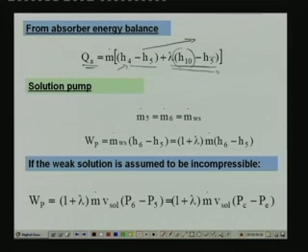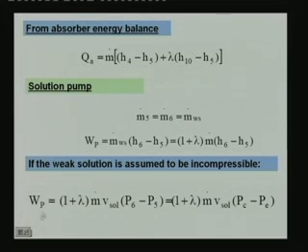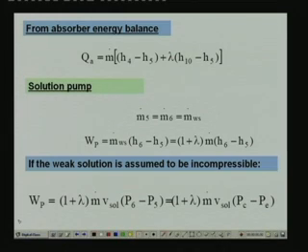So you can see that this consists of two terms. Normally, from the performance point of view, from the absorber size and all, this parameter has got to be low, because other parameters are decided by other performance related issues like your refrigeration capacity. So you can see that when the circulation ratio is low, the heat rejected at the absorber will be low.